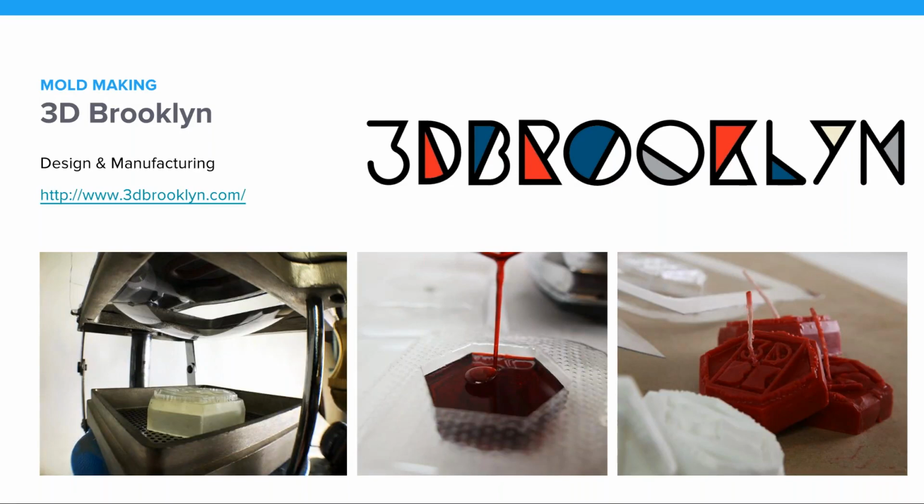They'll 3D print a mold. In this case, it was a mold printed on the Form 2. And then they put it in a vacuum forming machine all the way on the left. They pull a piece of plastic down over it. In the middle, you can see them actually pouring the candle wax into it. And on the far right, you have the final product. In larger production runs, they'll actually do several mold pulls. So they'll have maybe 10 of these that they'll all be pouring candle wax into at a single time. And that'll help speed up production.